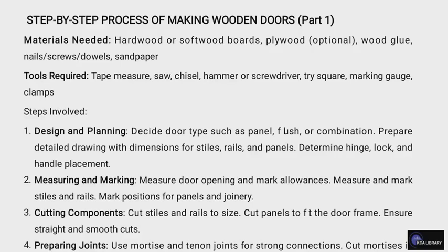The first step is design and planning, where you decide the door type, such as panel, flush, or combination, and prepare a detailed drawing with dimensions for the stiles, rails, and also the panel. Determine hinge, lock, and also handle placement.